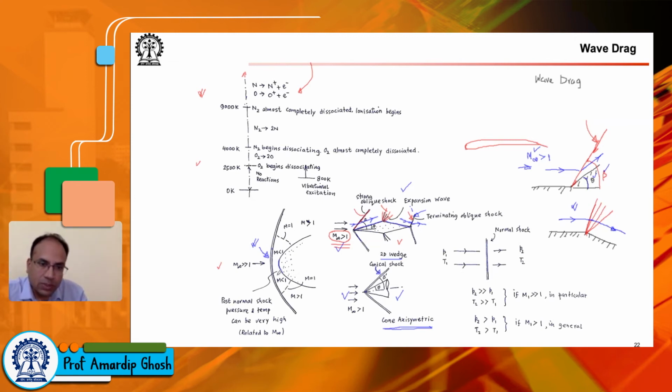But nonetheless, you will see that behind this normal portion of the shock wave, this is still supersonic flight. This one is something we say is a normal shock wave, normal to the direction of the flow. And these are oblique shock waves. So these become more and more oblique to the direction of the flow. So if the flow direction is like this, you see these waves are not normal to the flow direction, right? So in this region, flow direction is like this.